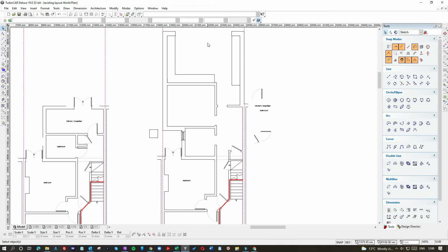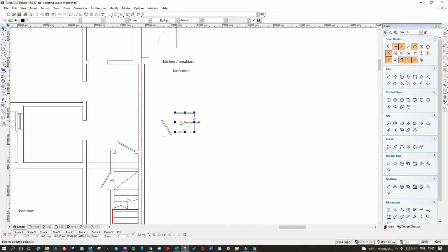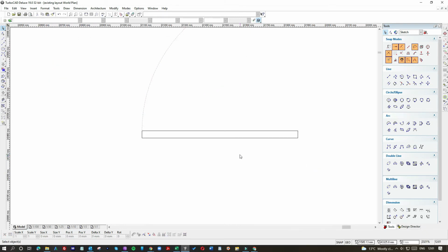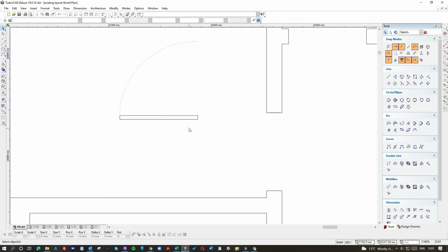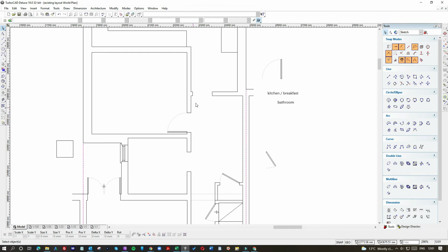So now what we want is our double glazed aluminium. But before we do that, let's just pop these doors into the bedroom and bathroom. So if we swing that around, right, so again, if we get the D, and let's see if we can get it to snap. There we go, that snaps. We're going to do likewise in the entrance to the kitchen.